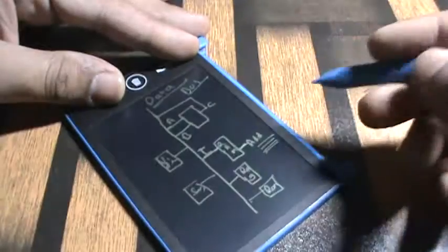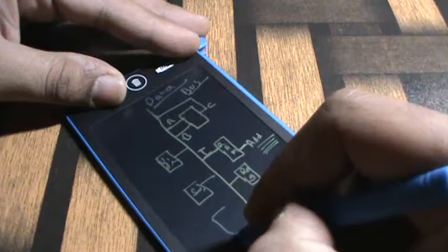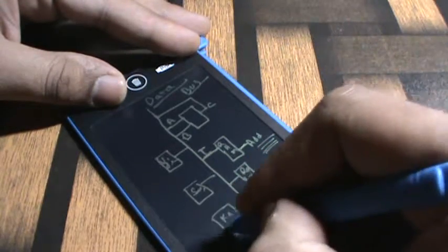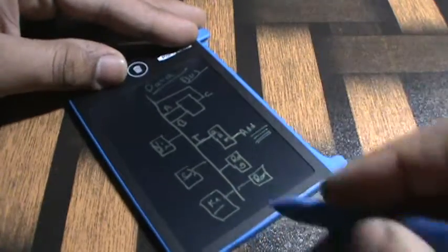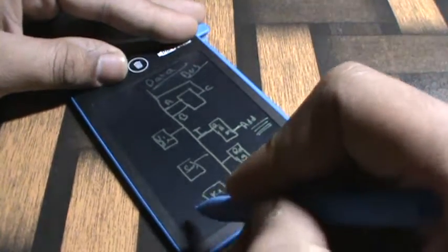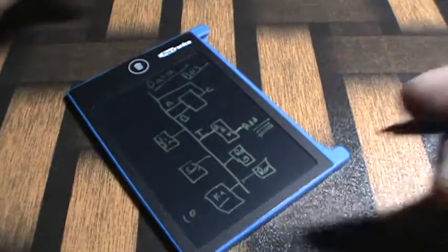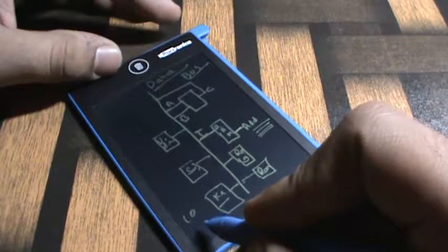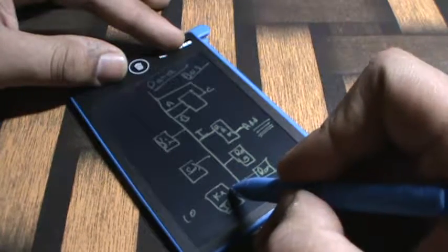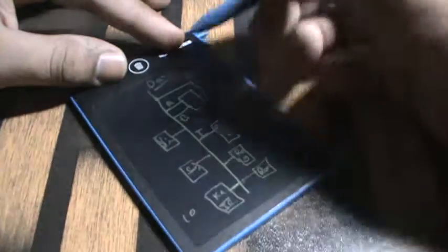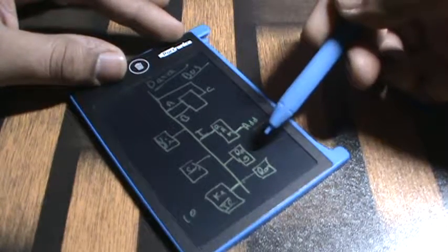So let's say we want to set a value of A. There is going to be a keyboard connected to our bus. I'm just representing it with two numbers. This is a keyboard, and on this keyboard we are going to give a number input of 10. That 10 is in decimal, not binary. 10 will be converted into an 8-bit number by the IC installed on the keyboard, and this IC is going to put that value 10 on our bus. So every component over here can access that particular value from the data bus.